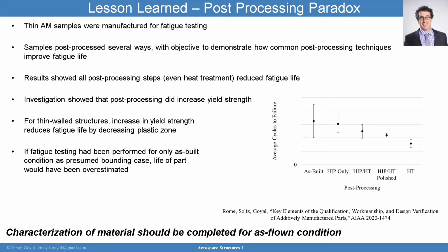What we like to do is the building block approach, like Vinay touched on, which is we start with small samples, a lot of tests, characterize material properties, then predict what happens with more complicated tests, validate that again, and then you can make your prediction for the full size structure. You're not regularly going to be within a couple percent. If you're within 5%, you're doing really well after all that testing. If you're within 10%, it's usually acceptable. If you're within 1 or 2%, I don't trust your predictions.